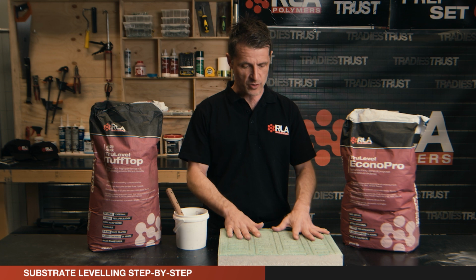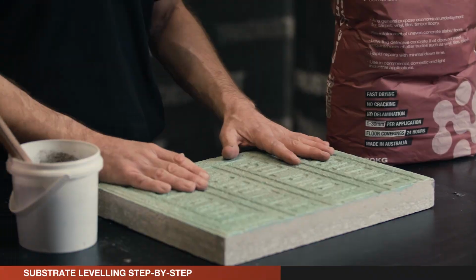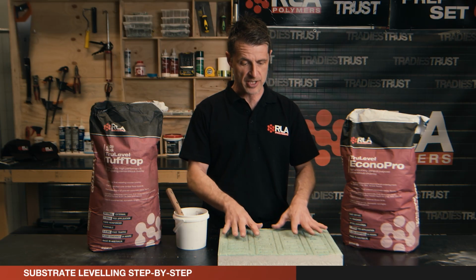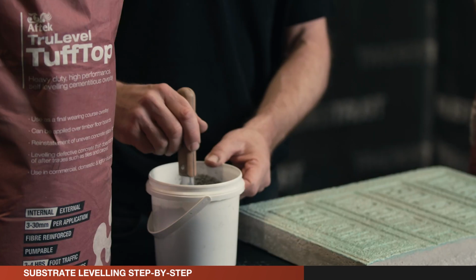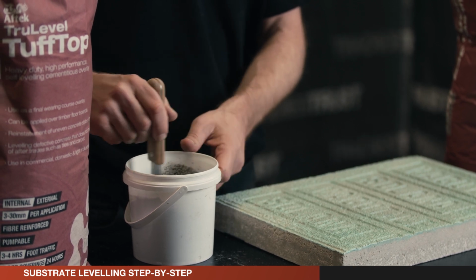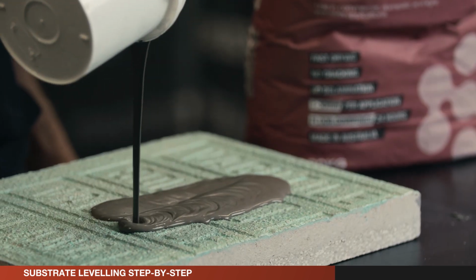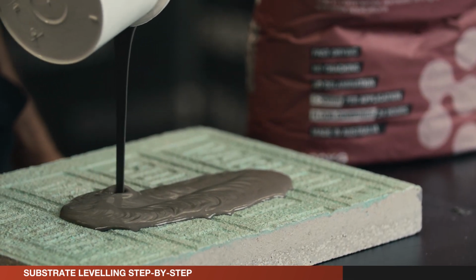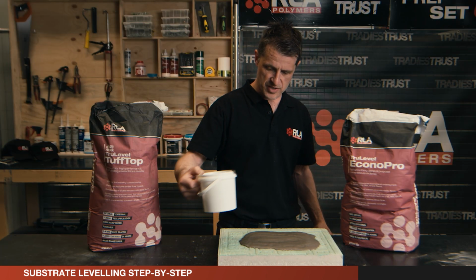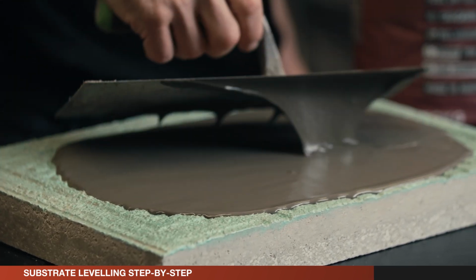Here we have a concrete surface that's been primed with a universal primer, which is used in conjunction with the RLA range of self-levelers. And we can see here that it's quite an undulated sort of surface, but we just mixed some self-leveler up previously and we'll just show how it actually pours out and the consistency of the product. So if we just pour it directly out and have a look. So as you can see, it's quite a smooth and fluid sort of consistency. Basically, it's applied to the surface and used a trowel or a gauging rake to sort of move it around and find its own sort of level.